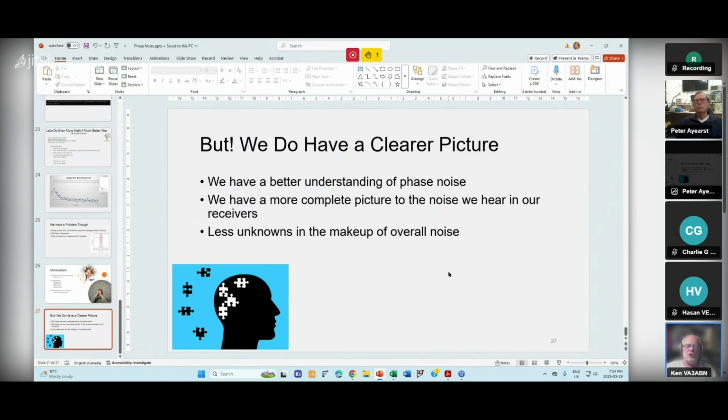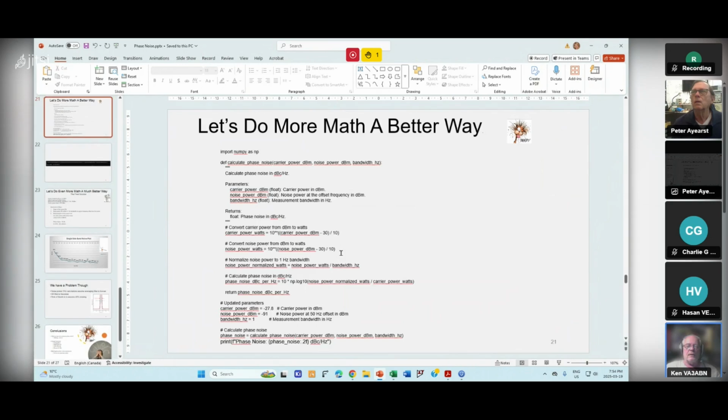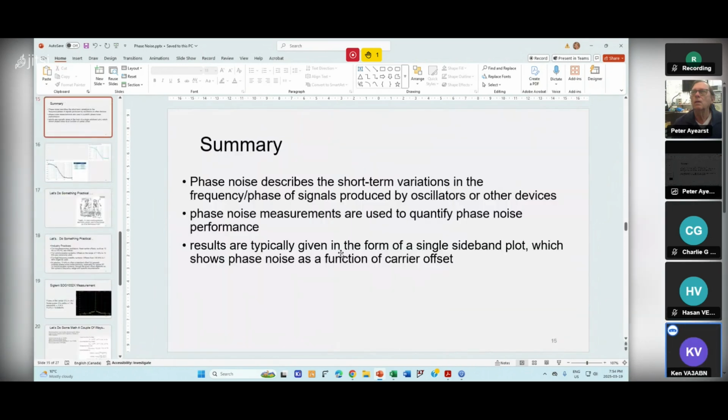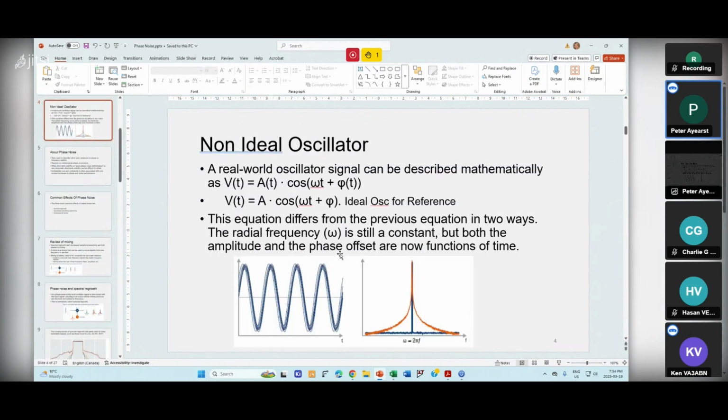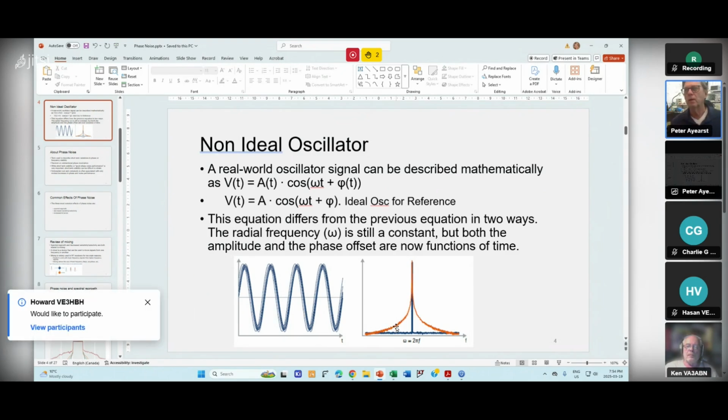Yeah. Is jitter considered phase noise? I believe so, yes. Okay, so that would be like you're looking at your scope and you're looking at a signal, and once in a while it jitters over to the left or right. Yeah. Where is it? Right near the beginning, I think it is. Yeah, you're talking about like right here. Yeah. If you got lots of phase noise, see, this is in the time domain, and this is in your frequency domain. So this is what the phase noise looks like in the frequency domain. And if you put your scope on this, then this is what you're going to see in your scope, and that's what you see with your jitter. Yeah.